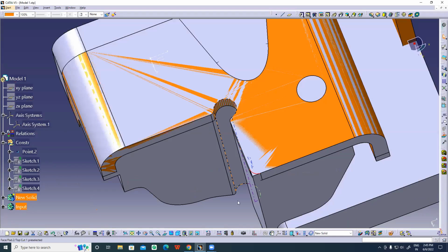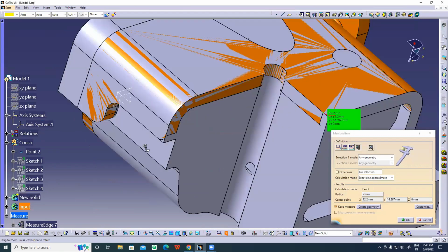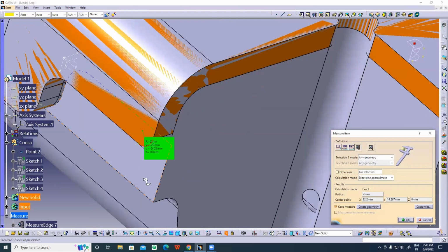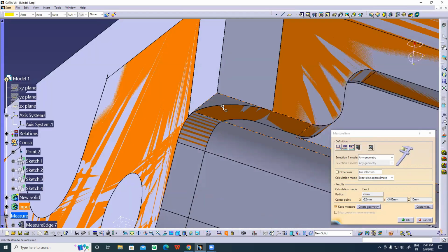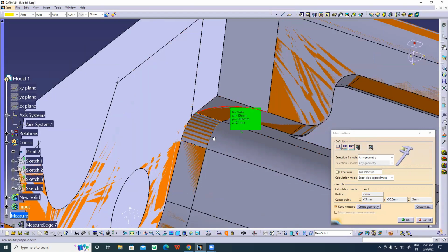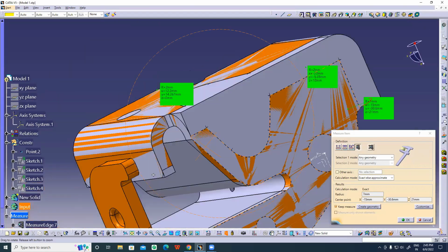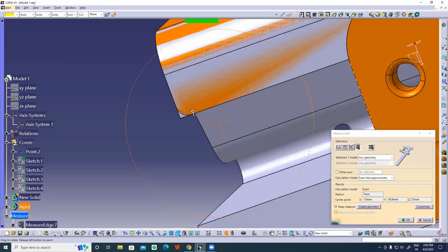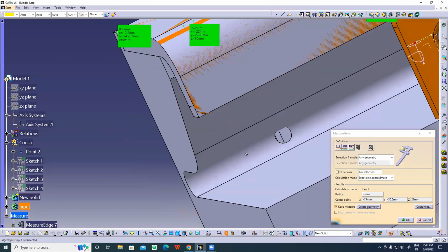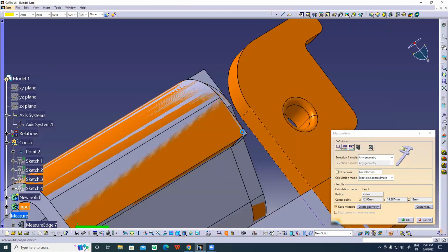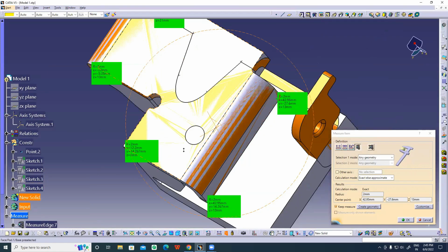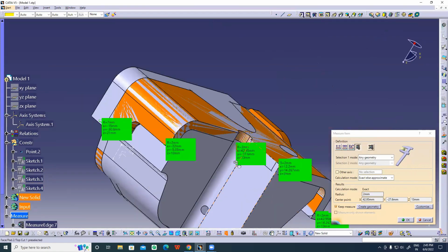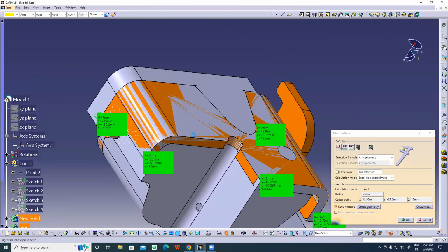We need to measure the fillet radii. So I'll go to measure 2 mm, and let's go to this portion. So 2 mm. Okay, and let's measure this edge, 7 mm. And where else do we have a fillet? I guess in these portions we need to apply a fillet, 2 mm and 2 mm. Okay, so remaining places I've applied a fillet. So okay, I'll just click on the OK option.